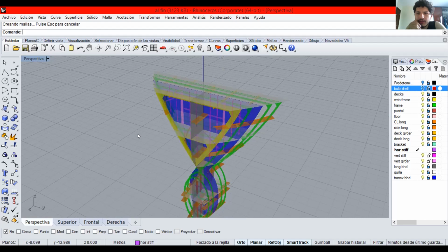It's like having the ship in the dry dock. In that case, yes, there is no water pressure. But also you could consider 75%, because if you take the ship to the dry dock, I don't think you are going to have that compartment full of water. It's empty when it goes up. Let's suppose that for some reason you have to put some water in to equilibrate or improve the trim of the ship. So I think it's a pessimistic idea to consider that it's 75% full. But in general, I would expect it to be empty. But in some cases, it could be possible that you put some water in order to improve the trim. And if you put it in the dry dock, there is no pressure from outside.